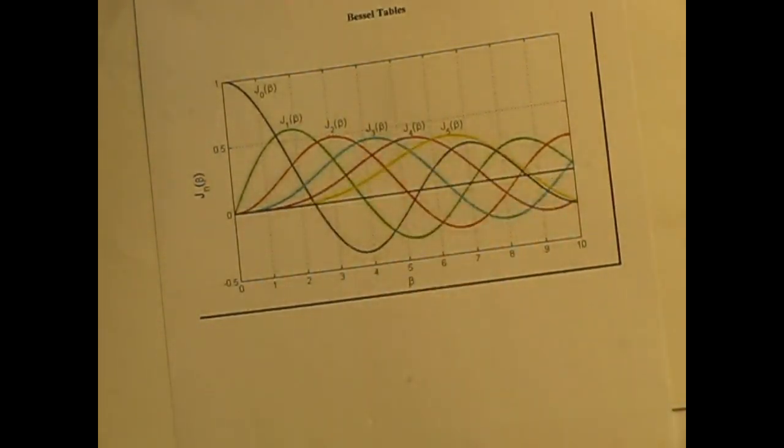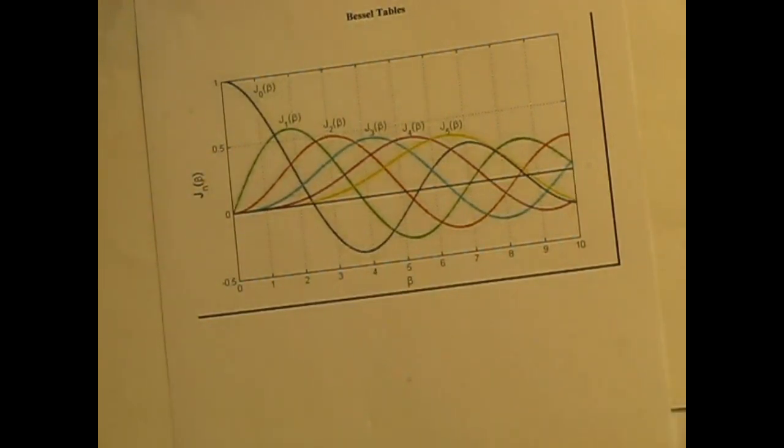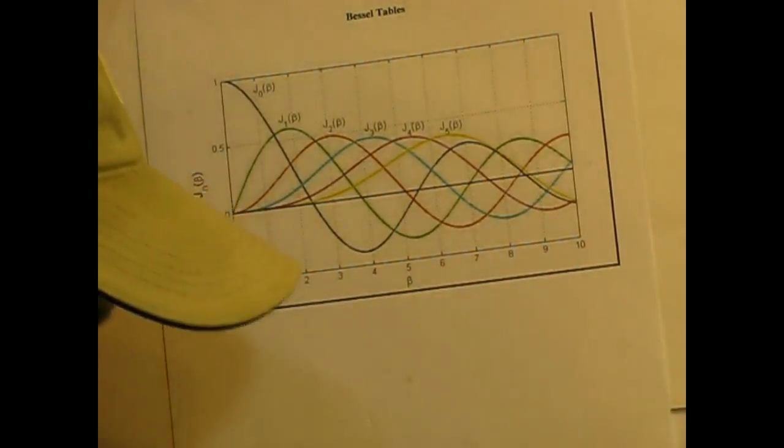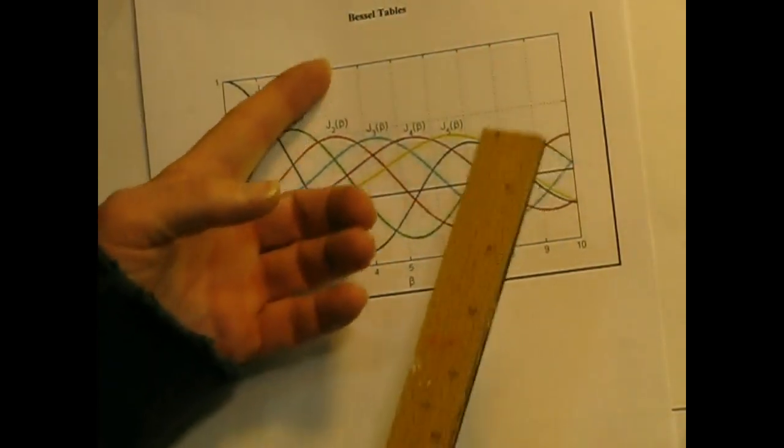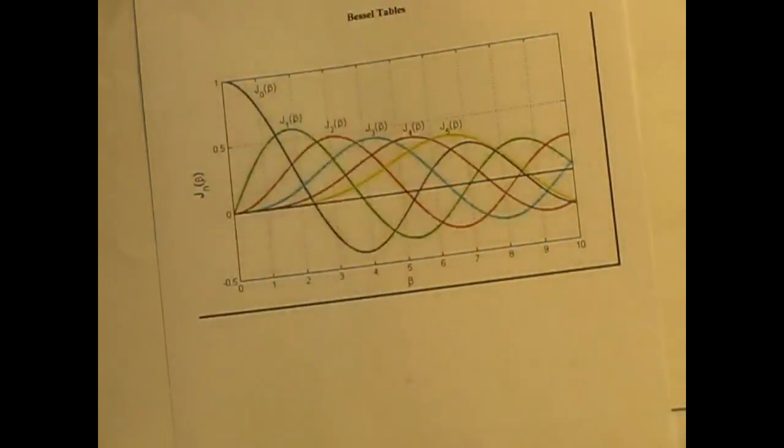So there's advantages to using an analog table here. I think it portrays things a little better, but it's a little bit harder to read and figure out what the actual relative voltage is, because you're interpreting a graph. And if you go to use this, it's always a good idea to put a straight edge here. So say you're at 3.5 at the bottom, you're also at 3.5 at the top. So you can get a better idea of what the sideband pair voltages look like.